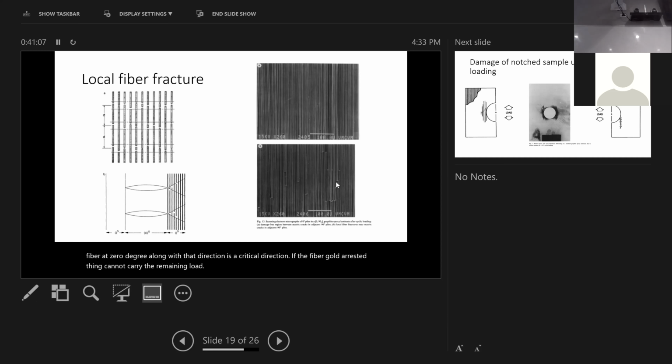Reifsnider also proposed you focus on this layer. When you do analysis of fatigue life prediction, you basically predict the remaining strength of this layer. You treat the other layers as expendable. Once those layers are spent, you calculate the stress redistribution and the remaining stress on this layer, and you use this layer as the critical element to do the fatigue analysis. That's the basis of this idea.